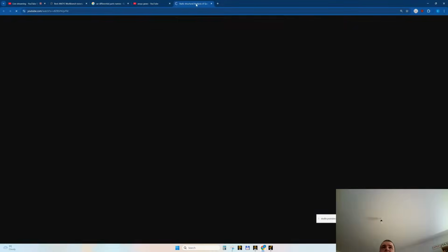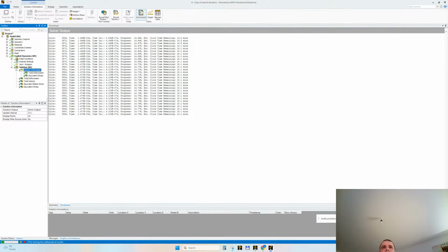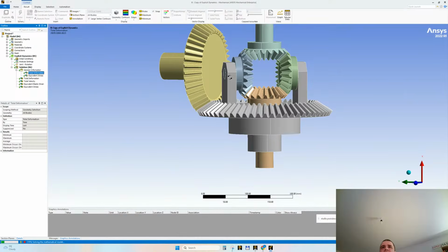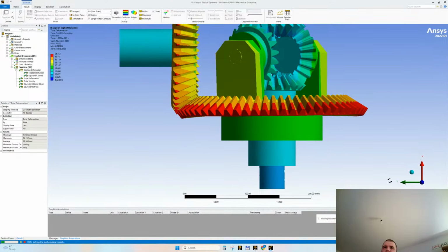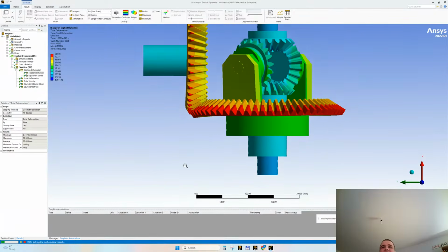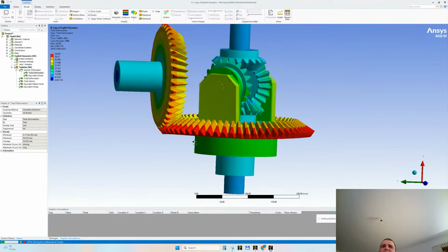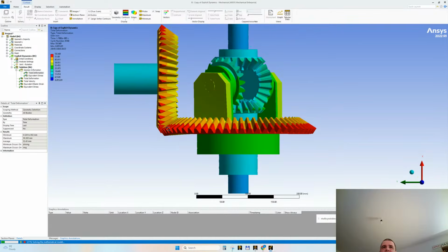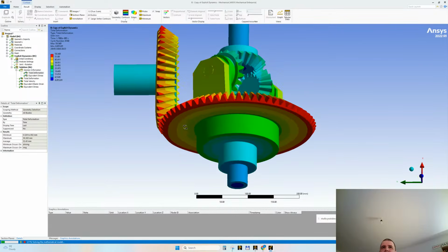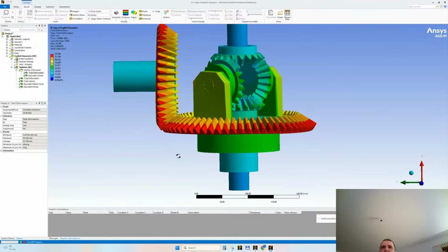Let's see if we have another bonded contact, out of curiosity. Do we have proper deformation? Let's see. Yes, finally. Yeah, it's nice, but this gear is very heavily loaded. This gear should be stiffer, let's say, but it behaves correctly. I think I can make this gear stiffer if I increase the thickness. Let's see.